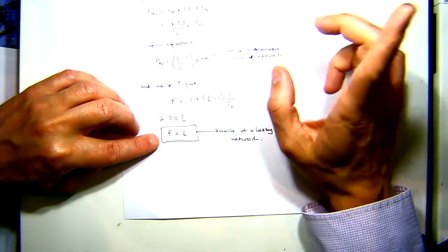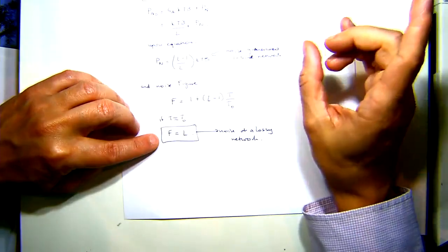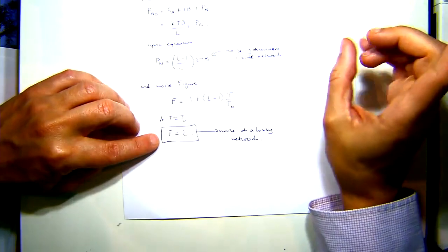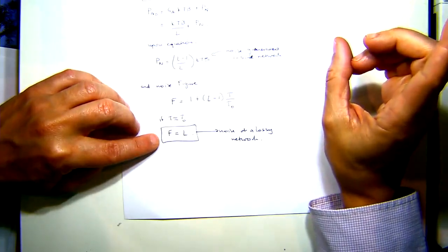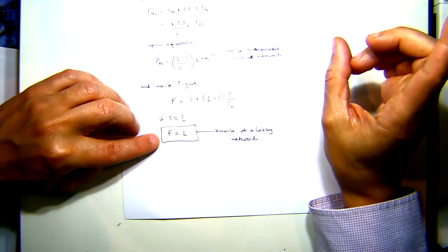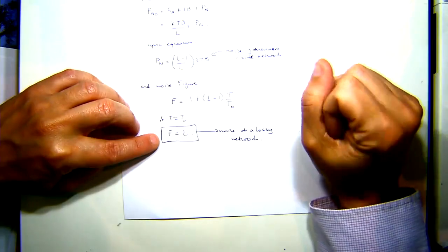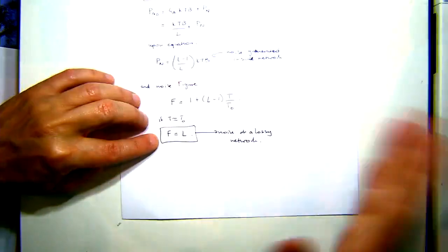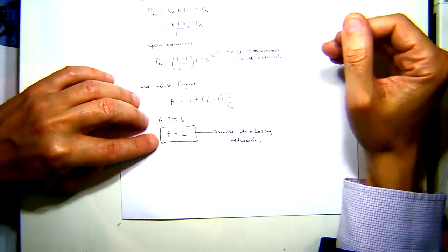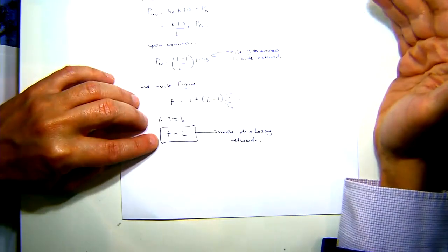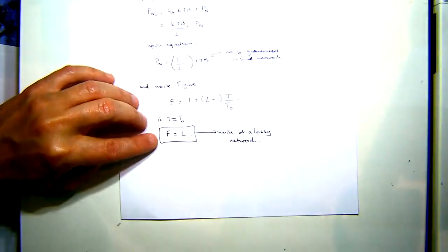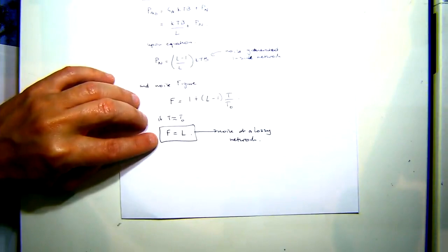So, for example, if I had a cable which had 5 dB of attenuation, what's its noise figure? 5. If I had a splitter which split the energy two ways and I got a 3 dB loss in power, what's its noise figure? 3 dB. Perfect. So the loss is equal to the noise figure of that component. All right?